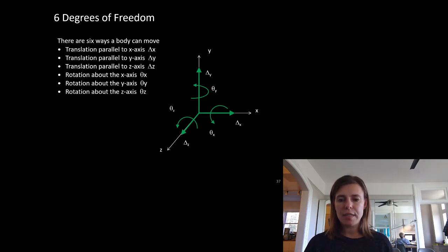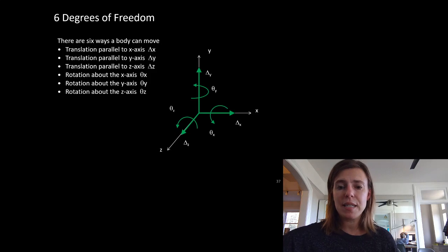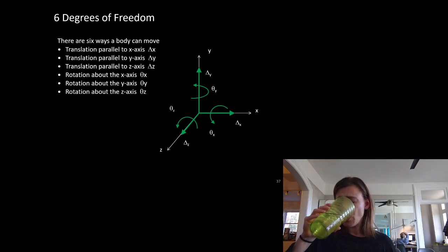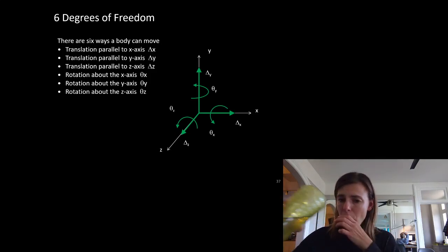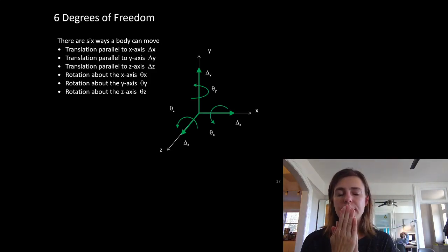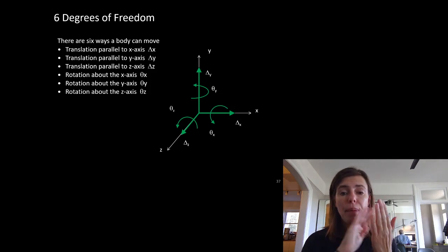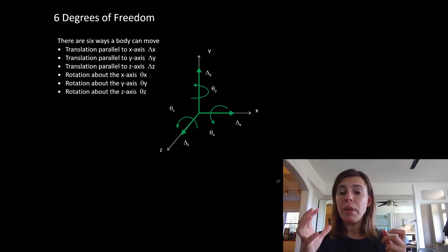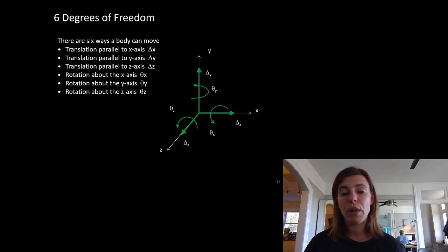Working in a 3-dimensional system can be a bit of a pain, so we'll often try to break it down into a 2-dimensional system, just to make our calculations a little bit easier. We acknowledge that it's an extrapolation or a simplification of the system that is a real 3D problem, condensed down into a 2D system. If you need to, stop and think about it in all 3 planes. But often, the way we're applying our loads, it's simple enough to break it into a principal axis at a time.